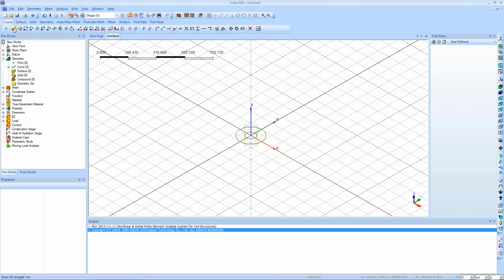After that, I'll create a line. I have to enter the coordinates. I'll input -60, 30 and the length is 120. Next is -60, -30. Length would be 120. Next is -120. I don't need to enter -120, 0. It's already understood. And the length of this line is 240 centimeters.